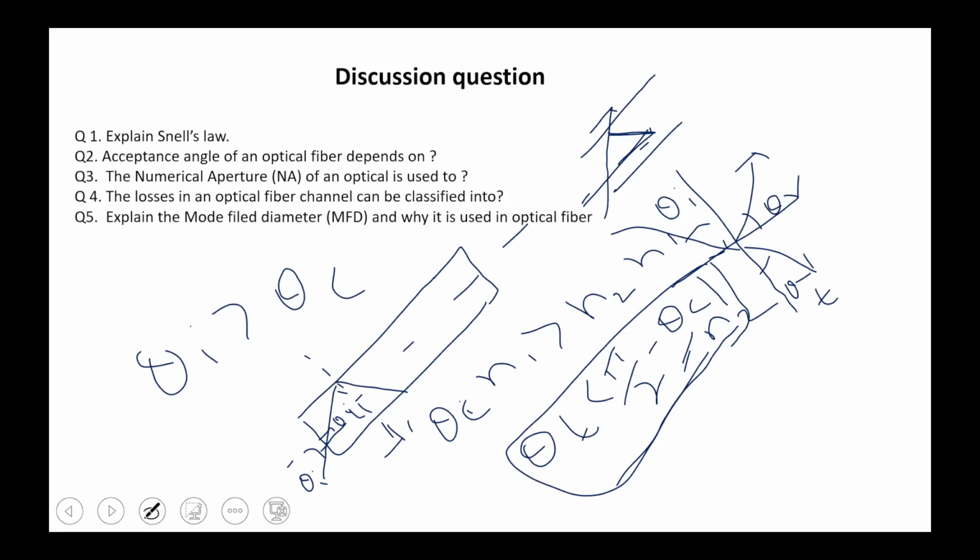Whenever you make a transmission of an optical line and put in some bends and joints, if there is a mismatch of the fiber, coupler, connector, splicing, or whatever is put between, like an isolator or circulator, and the refractive index is not matched, light is also lost in that case. Whatever input power you apply through the laser, the output power you measure at the output side will have some difference, which counts as a loss.